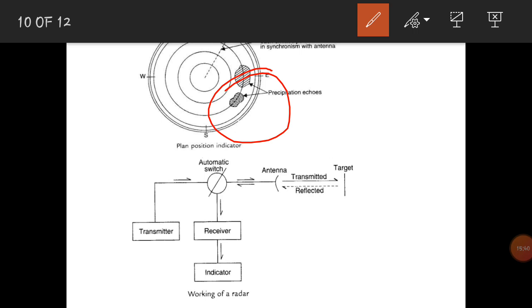When high accuracy rainfall measurements are needed, that is average error less than about 30 to 20%, the advantage of radar is diminished, since the number of gauges required for calibration is itself sufficient to provide the desired accuracy.